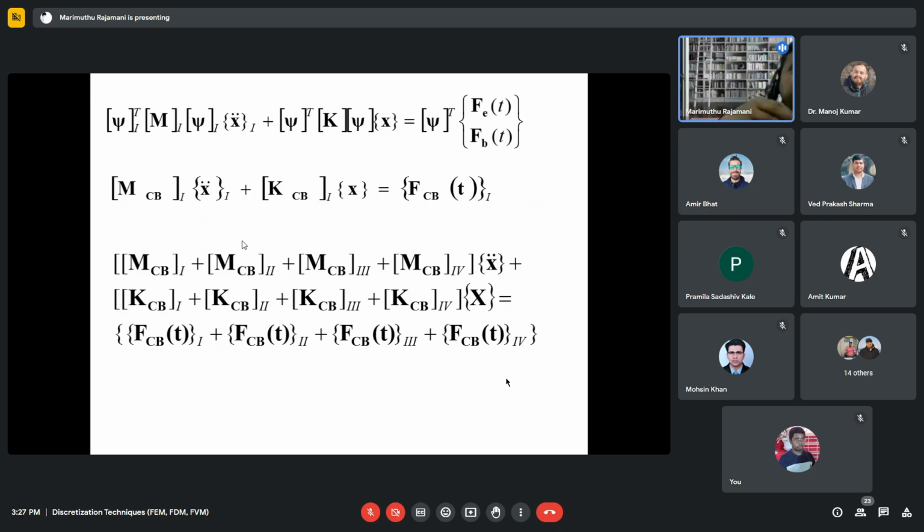Otherwise, you would model the launch vehicle plus satellite together, and when you do the dynamic characterization, you see what frequency and what mode shapes you get. Otherwise, by assembling the interface matrices alone with the launch vehicle, you will get the dynamic characterization.